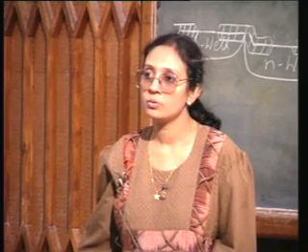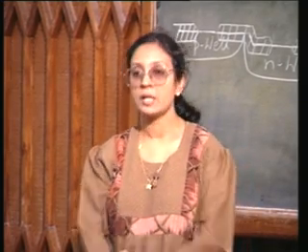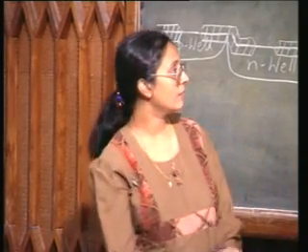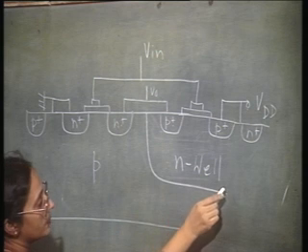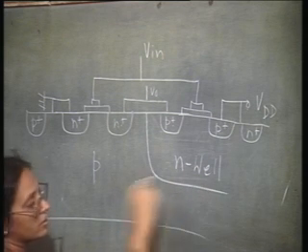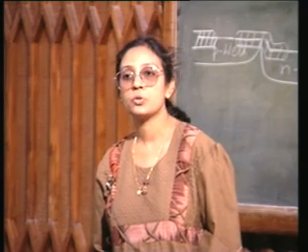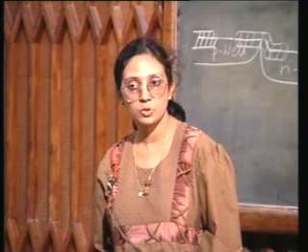What then can we do? We can have a buried layer, we can have an epi material, you can have this Nwell as a, you can have the substrate material itself as P on P plus type. Or what you can do is you can use what is called the retrograde structure. And what is a retrograde structure?